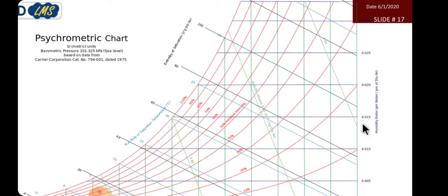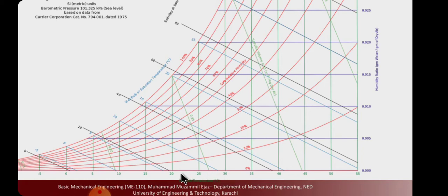So why is this condensing water coming? You see that the graph is moving like this. The amount of water molecules is decreasing, but the relative humidity is not decreasing. Why is it not decreasing? Because the air doesn't have the capacity to hold more water, and we are cooling that air, so the relative humidity does not decrease, but the amount of water is removed from the air in the form of condensing water.